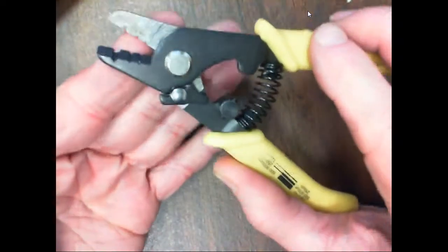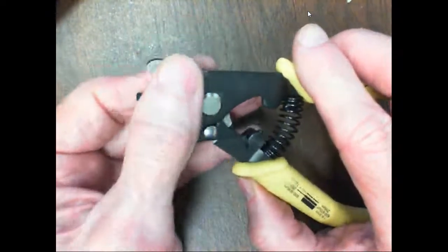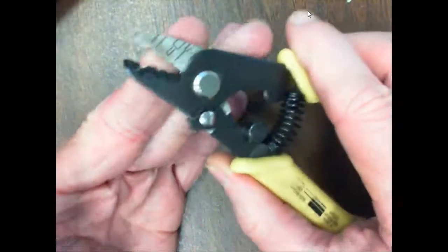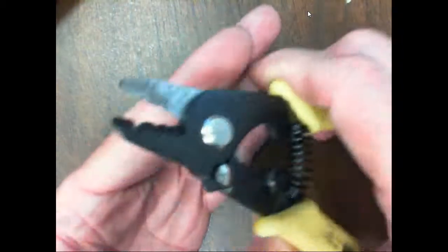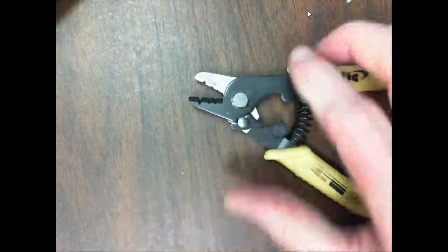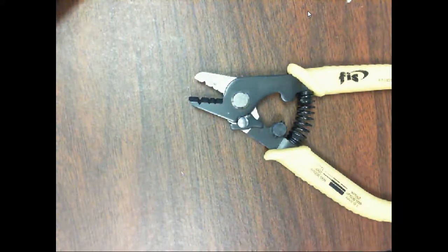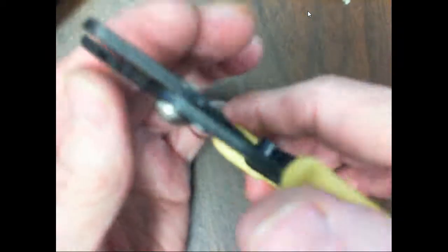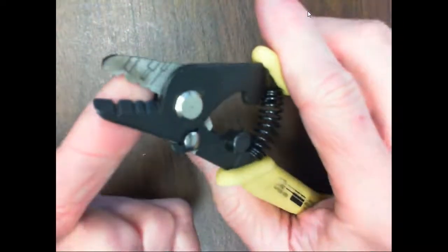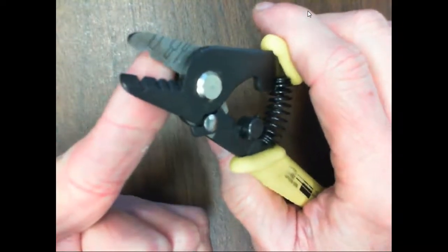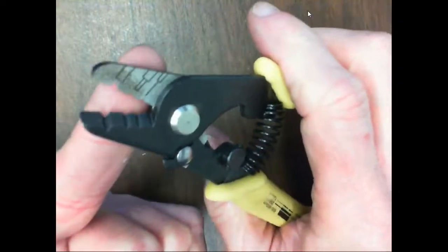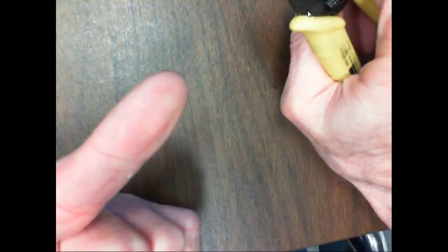Now these tools right here, if you use them right, notice for one thing, when I cut it, I didn't do it like this. I stripped it at an angle. You see I had it at an angle. So the blade is not going to hit this. If it does hit, it's going to hit it at an angle and just bounce off of it. It's not like copper. So you'll never see me come up here and do this, right? You understand? So notice when I did the outside buffer, when I did the tight buffer, I did my stripper at an angle. And when I did the buffer coating, I did it at an angle.